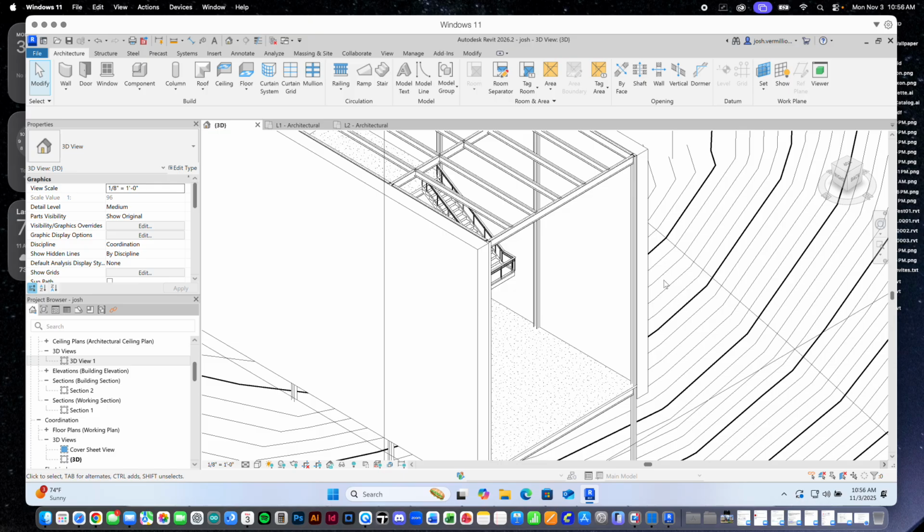Expansion joints, right? You guys know what expansion joints are? Okay, so yeah, because all of these materials will be heating up and cooling down, and therefore expanding and contracting at different rates, what we really want to make sure, especially around glass, is that we account for that movement and have something that can absorb it so that we don't accidentally crush our glass and start breaking glass.